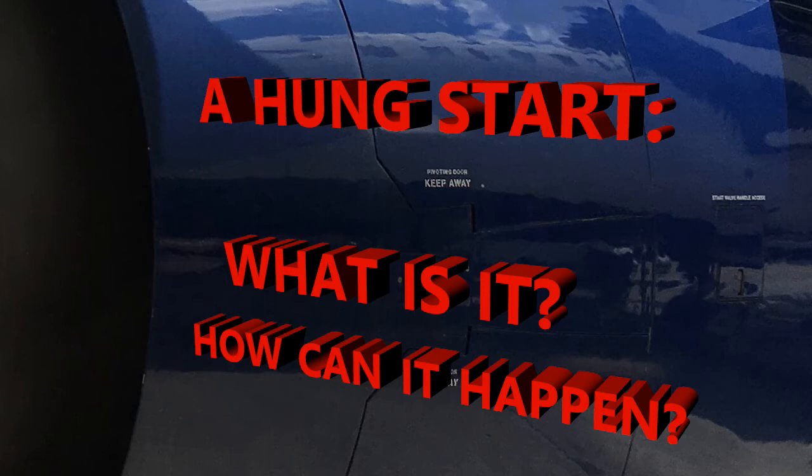situation is basically you're starting it up, but it's not translating to the engine. In other words, the engine's not getting to the idle RPMs that it needs to be. It's falling short for whatever reason, and that could be from a weak starter. That's just one possibility. But that's what a hung start is. You're doing everything there to get the start sequence going, but that engine's RPMs are not going up to where it needs to for idle.